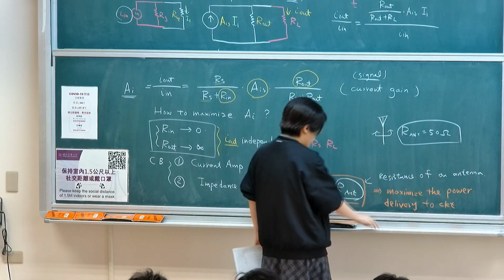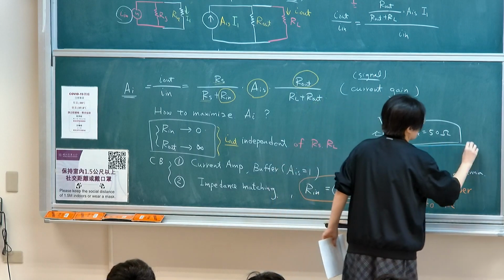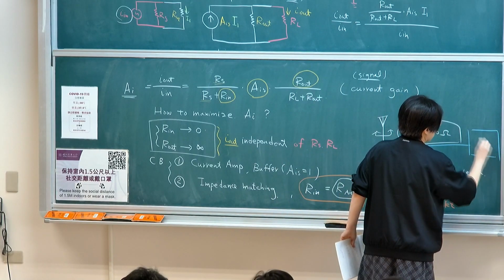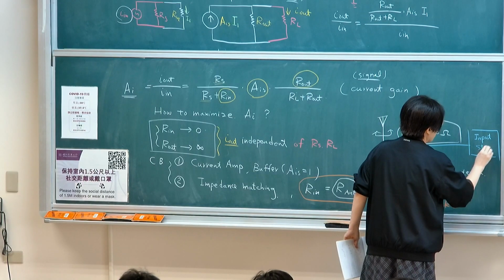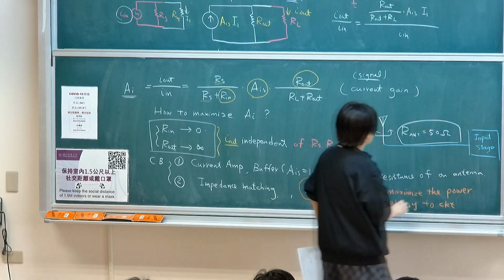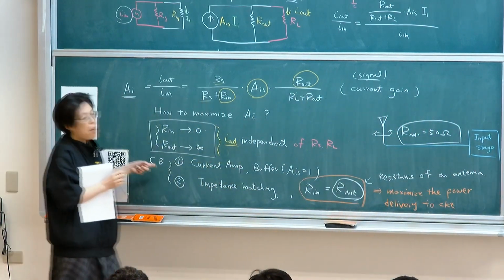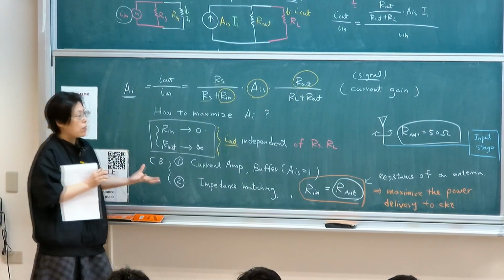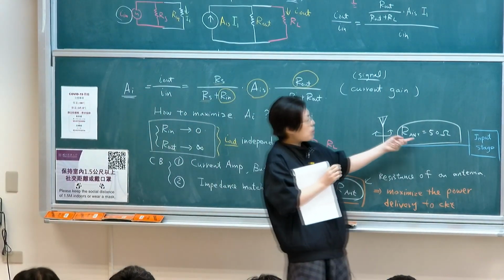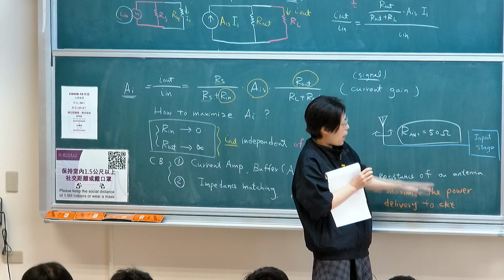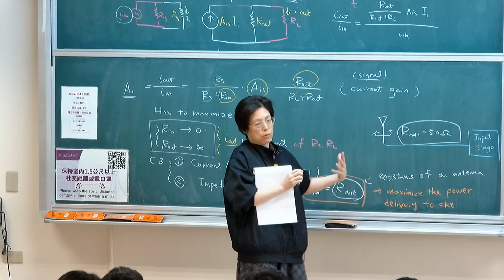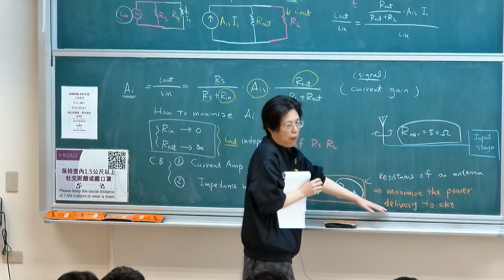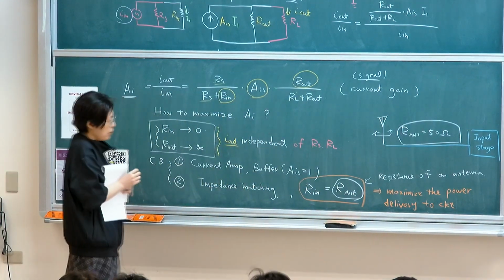If your antenna is connected to a circuit, this is typically called an input stage. In this case, you want to use a common base stage, because that allows us to change my input resistance to a low level, adjusted to match the antenna resistance, to take the maximum power for the circuit to operate.